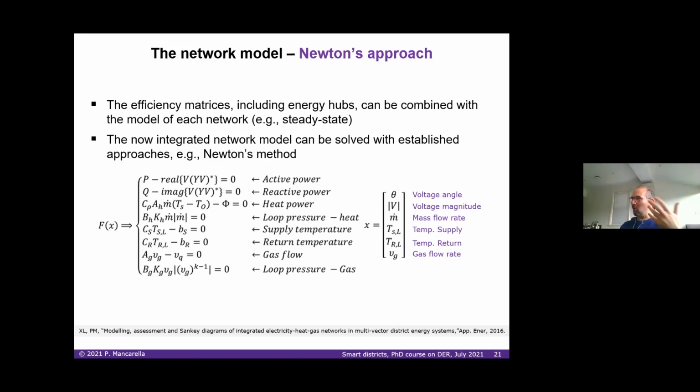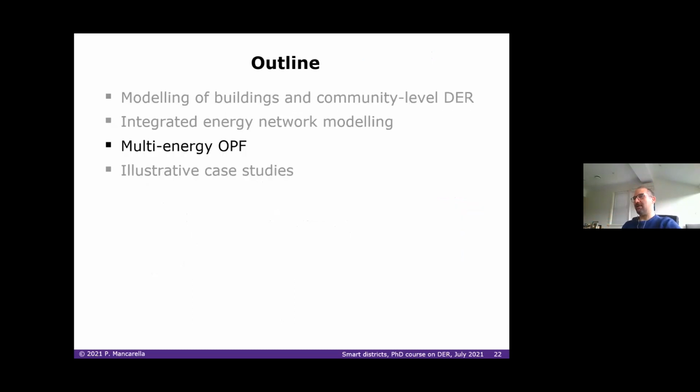So somehow all that was presented by Steve and Nando in terms of OPF and difficulties with the power flows and the convexification of that applies also for the other equations. And there is lots of work that has now been done to understand how what was done for the electricity system, where Stephen was somehow pioneering in terms of convex relaxation of OPF, can also be extended to other energy networks.